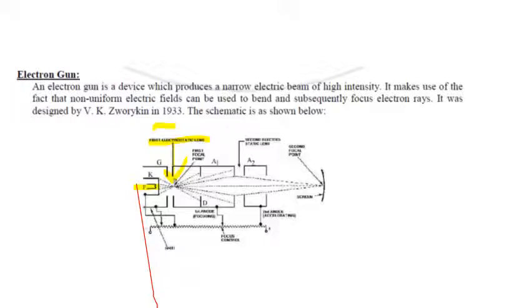This is the first focal point. Then we use several anodes here. And again the beam will spread because the electrons are negatively charged and repel each other. Anything which is at a larger angle will be absorbed by this slit, and the rest will pass through the anode. This is the second place where we focus the electrons. The electrons move towards the screen from here.